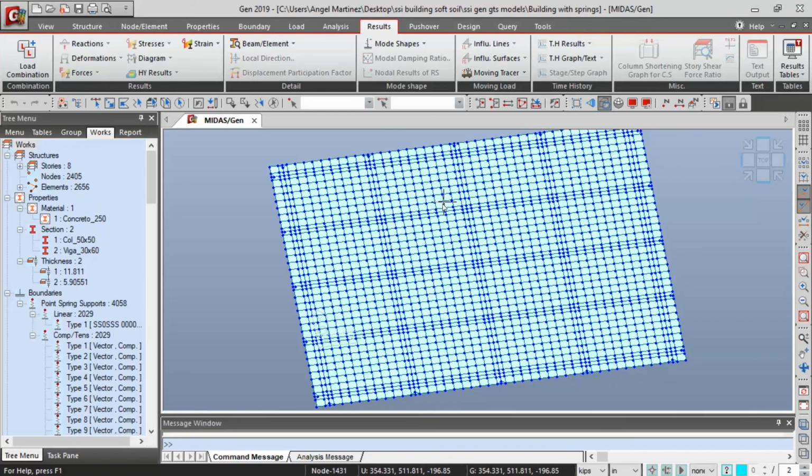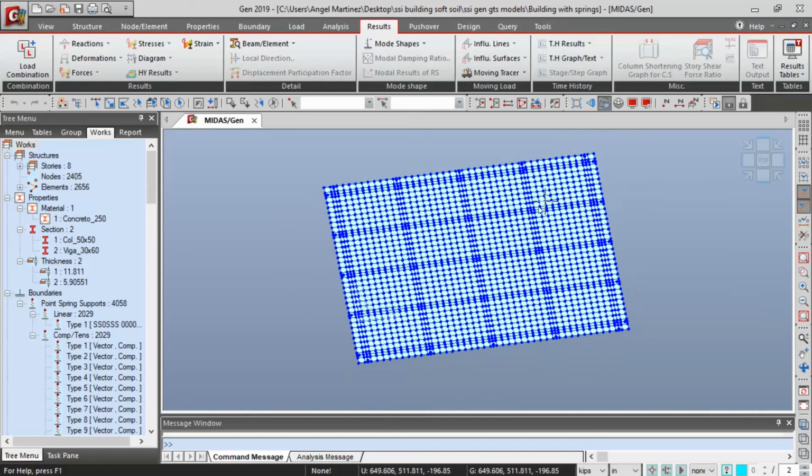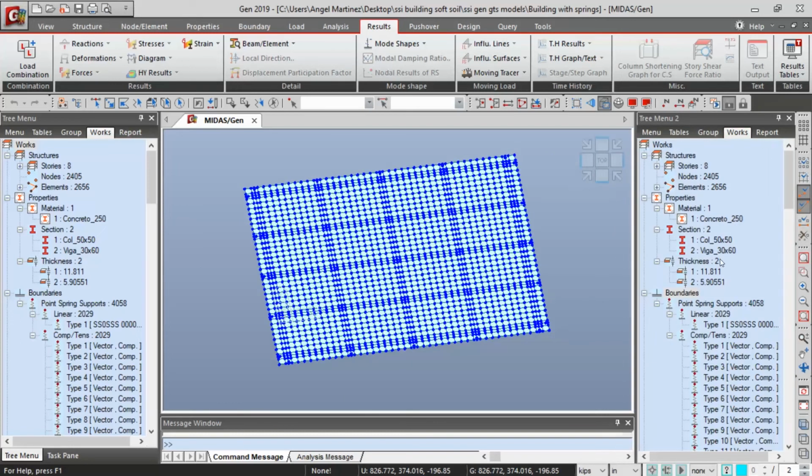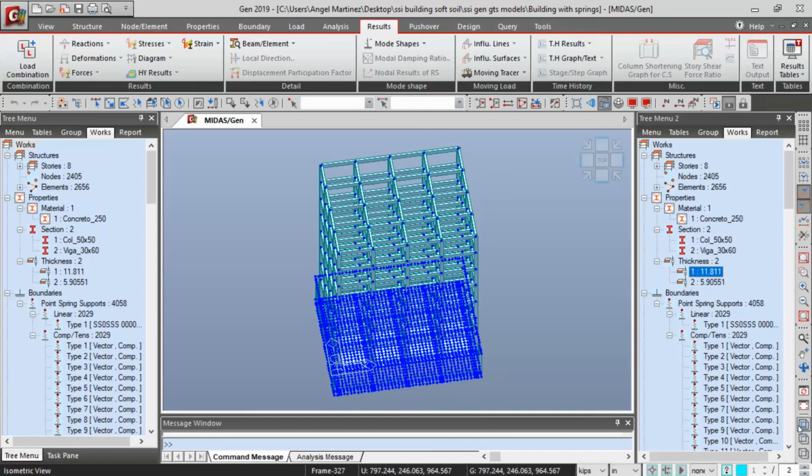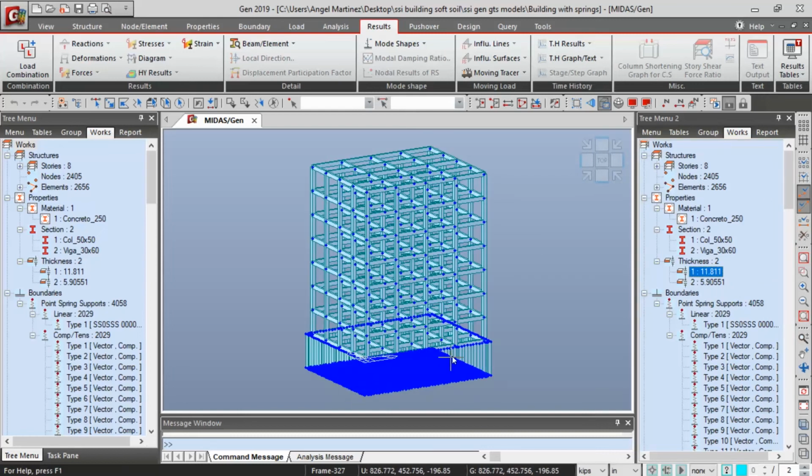So that might be something that would be a lot easier to just redo within the Geotech software, and we can just focus on only exporting the superstructure components that are more difficult to model manually in the other software. So we can end up just selecting or deleting sections of the element and only bringing it down to the core, which would be just the columns and the beams and the load combinations.